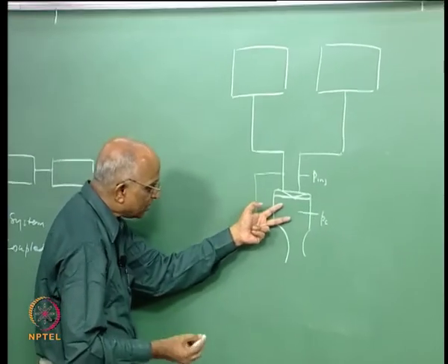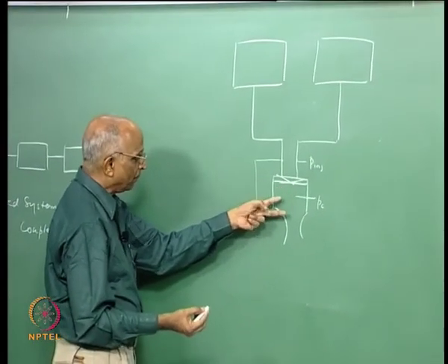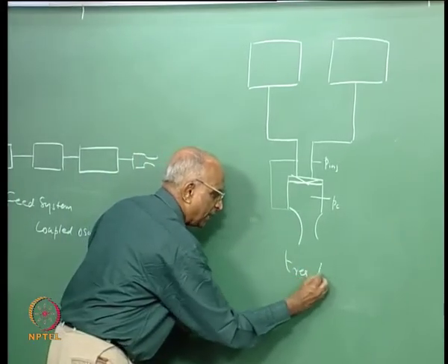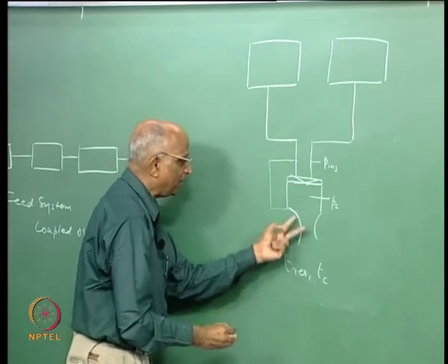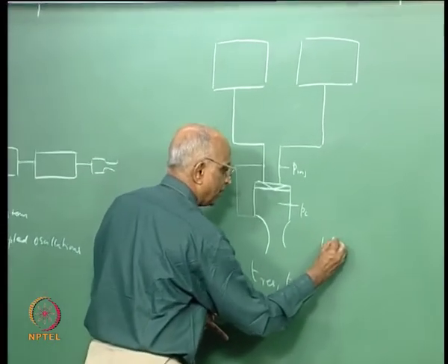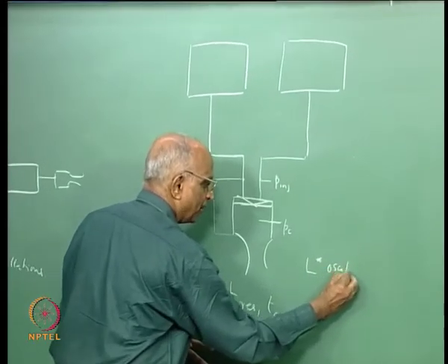That means the feed system is influenced, and such type of oscillations are known as feed system coupled oscillations. Therefore, the oscillations depend terribly on T residence and time delay. T residence depends on the L star of the motor, therefore some people also call them L star oscillations.